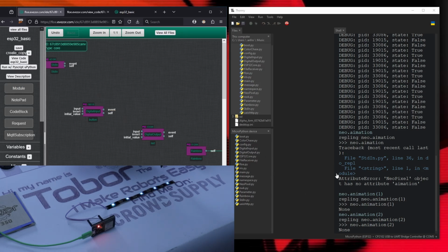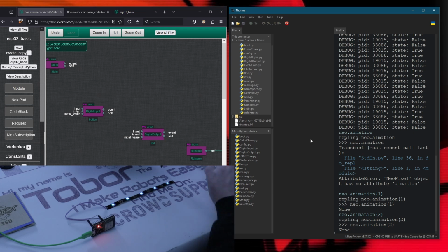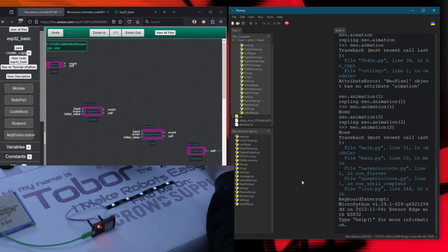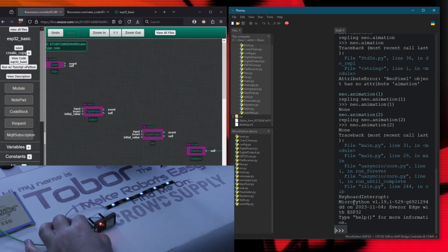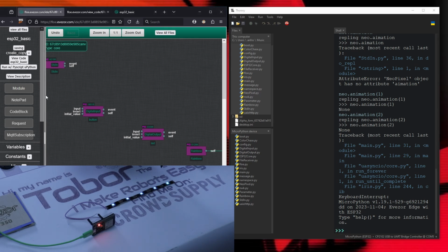We have our program over here. It is running. Let's go ahead and stop this. So we're going to press Control-C. And you can see here that now we're actually at the legitimate REPL prompt here. You can see that when I push the boot button, nothing is happening anymore. We have now stopped our ESP32, and we have changed this, and we want to change our program. So we deleted the link between the button and the LED. Let's go ahead and save this.